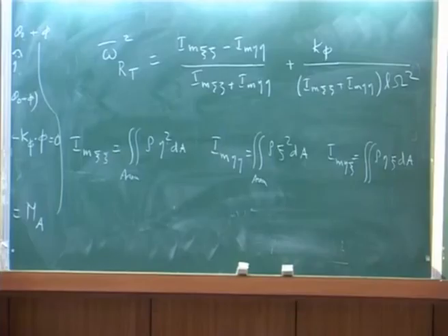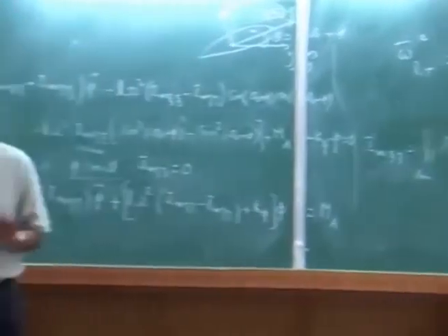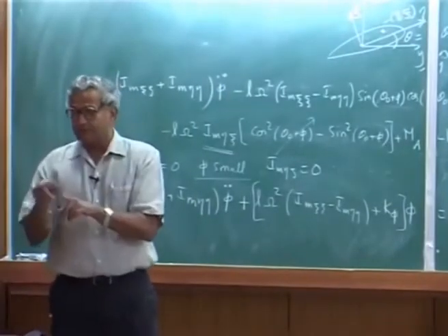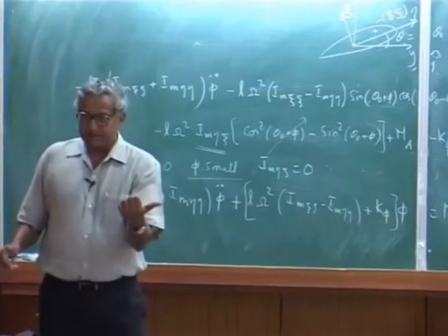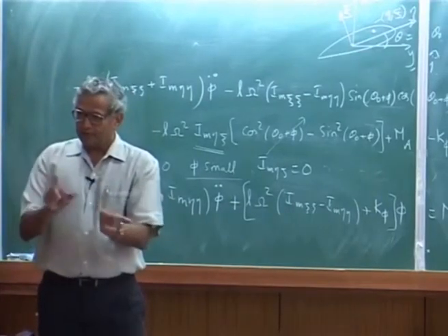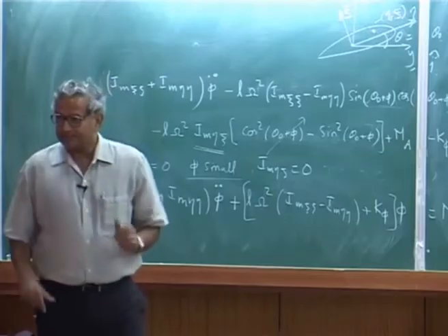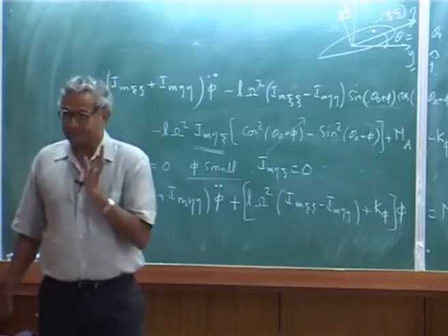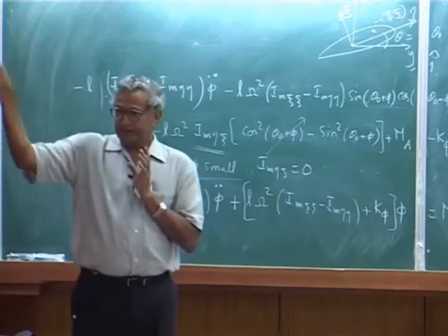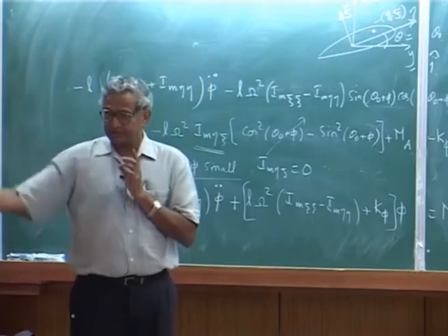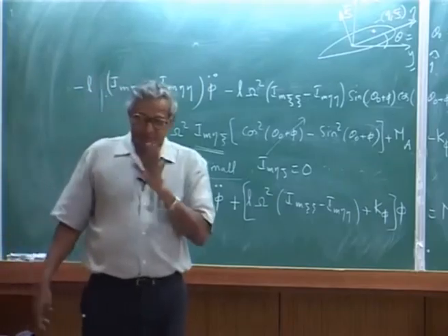Location of feathering axis 25%, that is all. No, in rotor blade now you see they do not want to keep the CG away from the elastic axis, feathering axis. If you keep the feathering axis separately, aerodynamic center separately, mass center separately, then you will have lot of coupling, flap, pitch coupling, everything will come. Because when you flap up, then inertia force will be somewhere else, that will give a twisting. So, you do not want to do that.